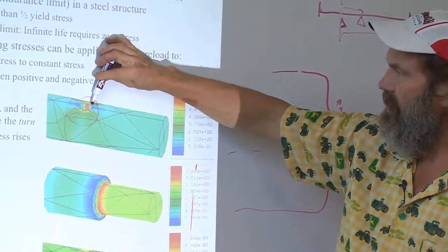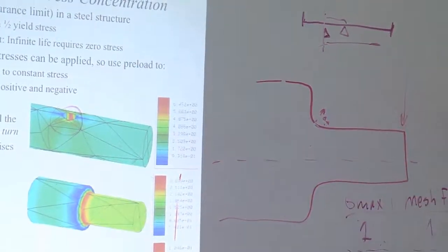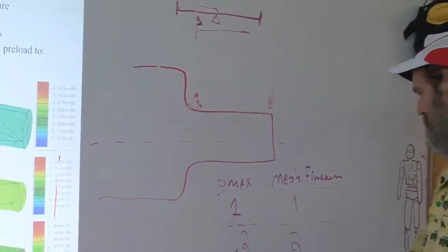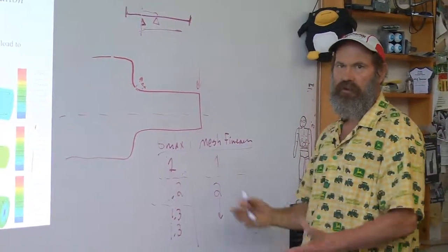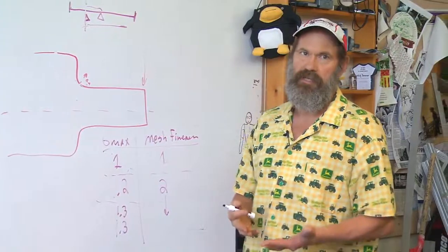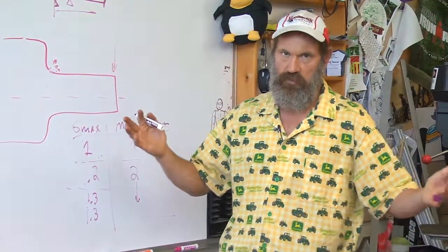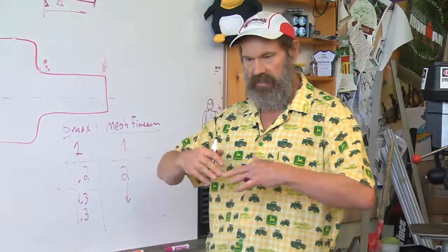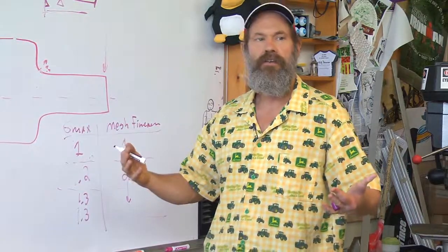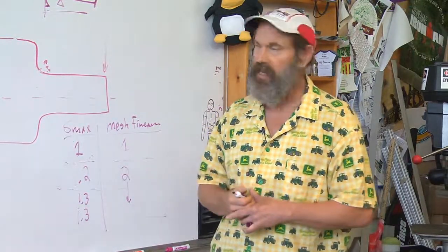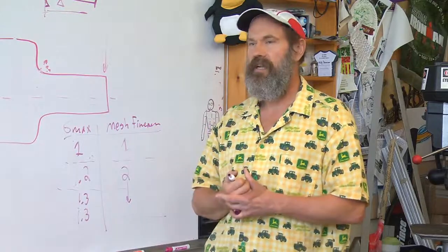And you say, well, why if I'm doing this fine meshing and I've got that hole, why do I bother to do this? Why not just start with a very fine mesh to start? Because it takes a lot more computation time, even in today's world of super fast, wonderful, marvelous computers. As the structure gets more and more complex, it can really start to drag down the analysis, particularly when you start wanting to play what-if analysis.